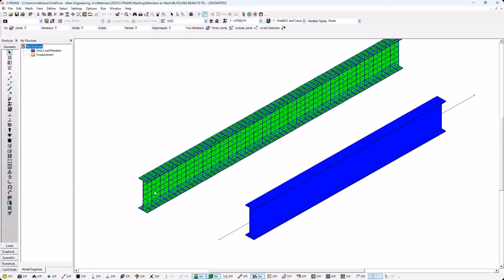In the shell element model, we've got plenty more nodes, and shell elements with a defined stiffness and material property to characterize the stiffness between each end of the member. But obviously with this, we have a lot more decisions to make related to where our boundary conditions are, for example. If I look at my supports on this structure, you can see that we're assuming a fully fixed support on the one end closest to the screen, and it's cantilevering in the other direction.